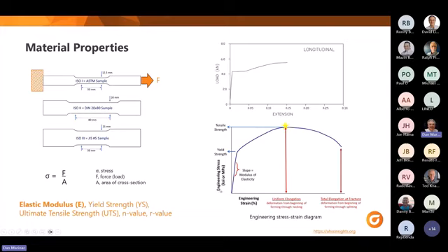What's important on the stress strain diagram, and I'll use engineering stress and engineering strain here as opposed to true strain, which I'll get into in a minute, is that I think we've all pushed on the side of, let's say, a pop can and let it crinkle back and forth. When it bounces all the way out, you're in the elastic portion of the curve. Once you've pushed on that side of a pop can or a soda can so hard that it stays deformed, you've now entered the plastic portion of the curve.